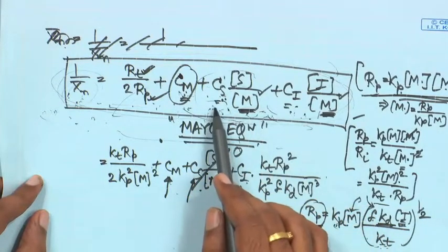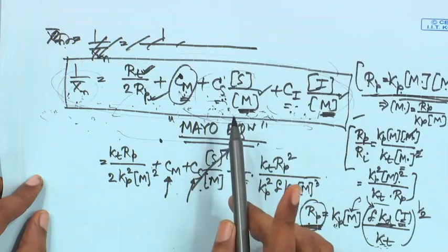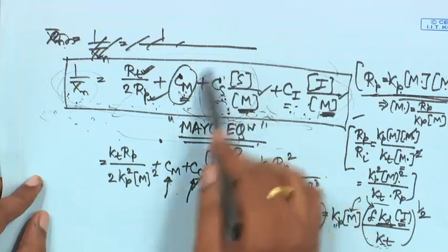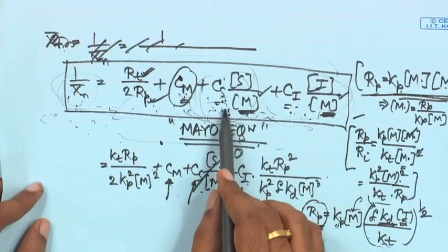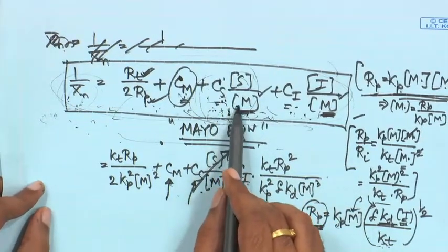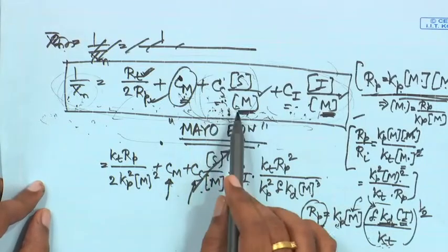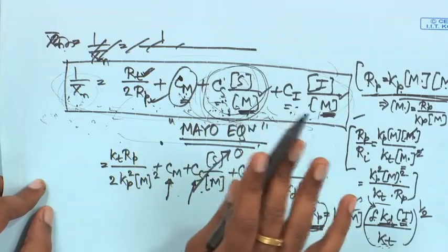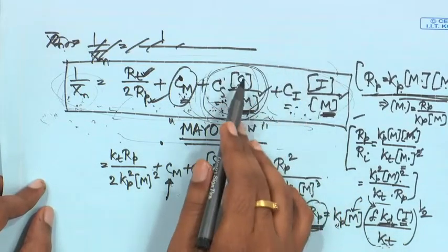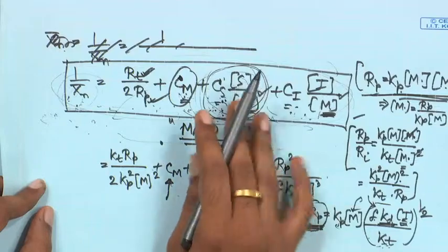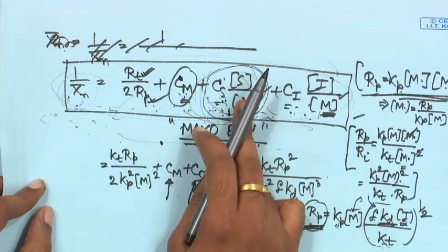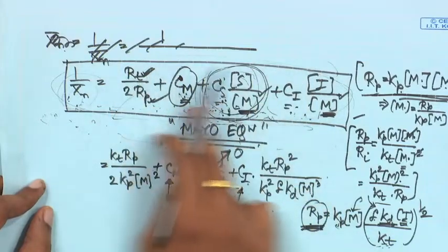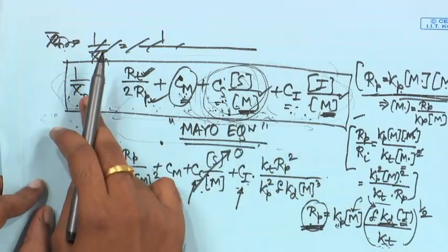We have neglected Cs by saying, number 1, there is no chain transfer to solvent, although this term could originate from there of course, and number 2, we have not added any chain transfer agent. Now, let us say there is no chain transfer to solvent and we are adding a chain transfer agent, then this term will tell you the contribution of the chain transfer agent to limiting the value of xn bar.